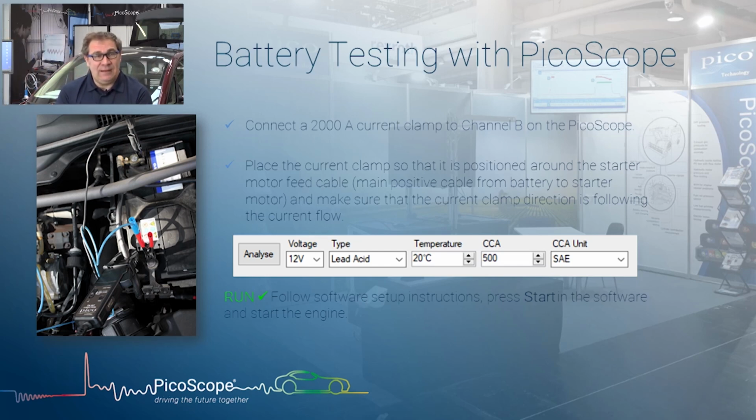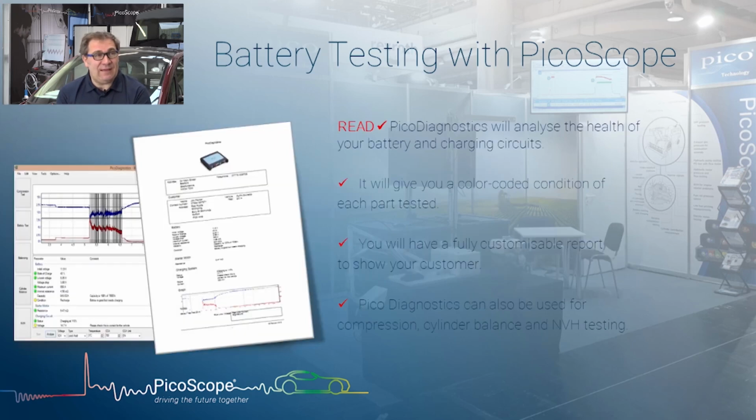And then we run, start the engine, and it basically analyzes the condition of the battery and also the charging and starting systems. We will then get this sheet, and these are your 2 waveforms, the same as you would have seen them on the normal oscilloscope software, but then we've analysed them. The software has analysed them: green is good, amber might be something you want to look out for. And of course, if we end up with a red dot, then we know we've got a problem somewhere within either the battery or the charging and starting system that's going to need attention.